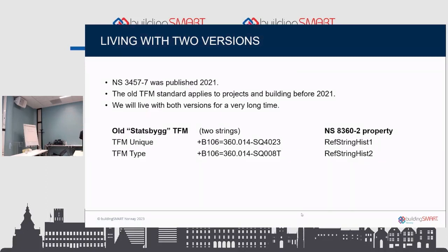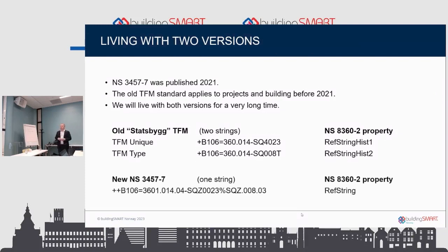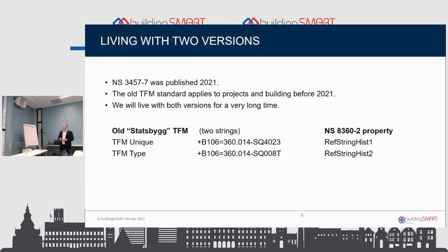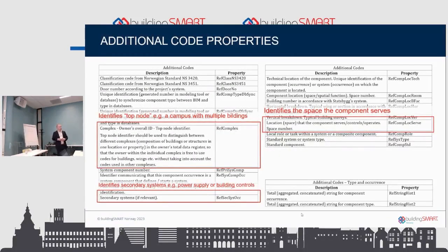If you use this coding system in IFC files, for example, you can have an air terminal, and it can have a relation to this room, but the air terminal does not have the object property inside itself; it's the relation definition. The air terminal would be part of the system, and you can see that it serves this room, so you can have the code of this room in this property.